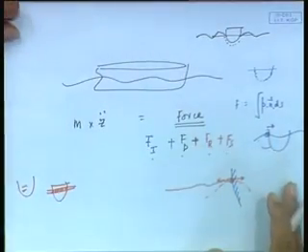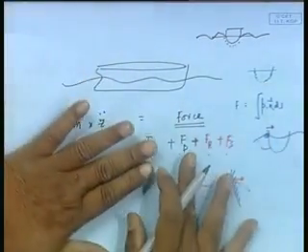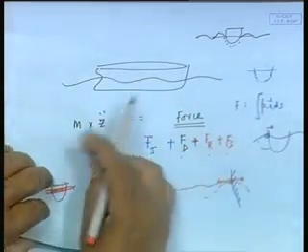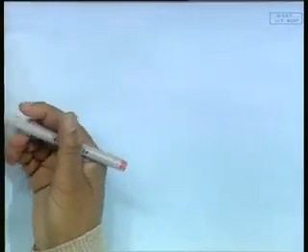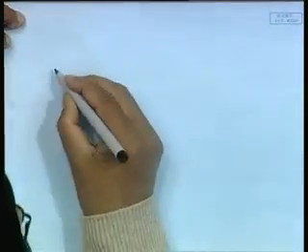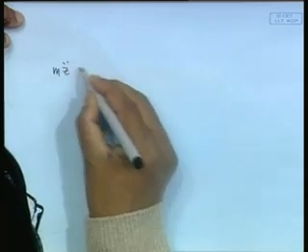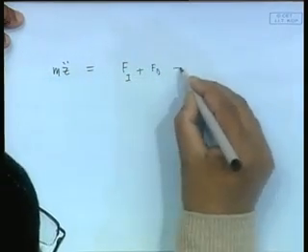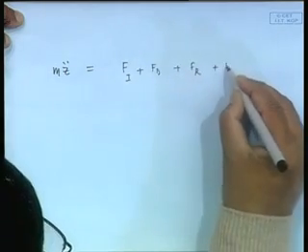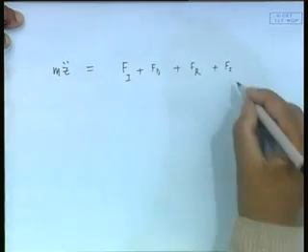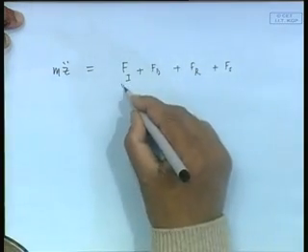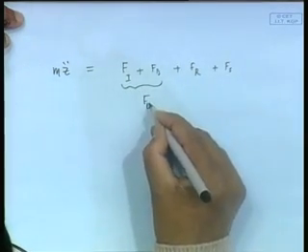Now comes the interesting point. What is happening now? I will go to the next page and try to work on this part and see how this equation of motion comes about. So we end up getting something like Fi plus Fd plus Fr plus Fs, F hydrostatic S. Now here this is my incident wave force. These two together are quite often known as Fe.